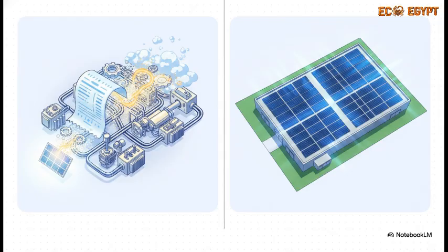But for large commercial and industrial facilities that operate under a net metering scheme, we generally lean on the other approach, the consumption method. See, because the grid essentially acts like a giant battery under net metering, we can just look at the client's annual energy bill, pinpoint their exact energy demand, and mathematically work backward. We account for all the inherent system losses to figure out the exact size that solar plant needs to be to offset that specific load.